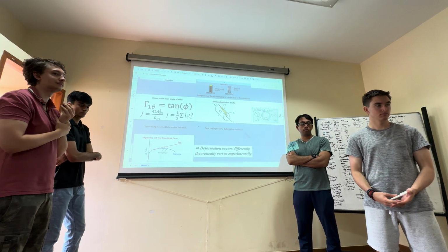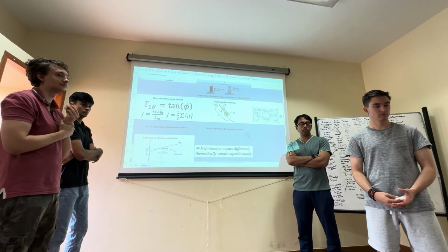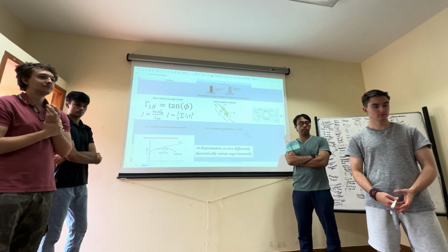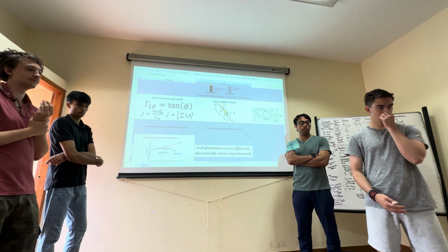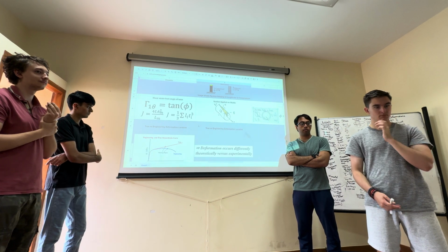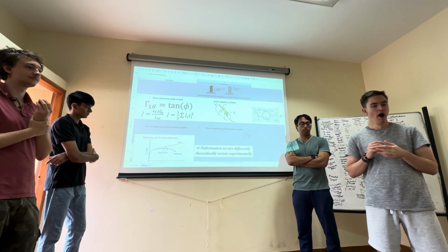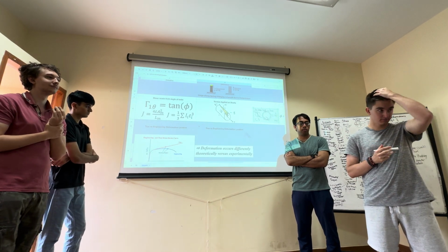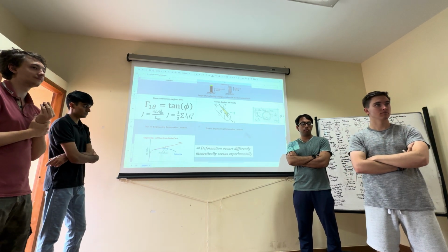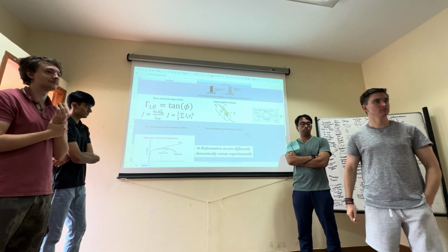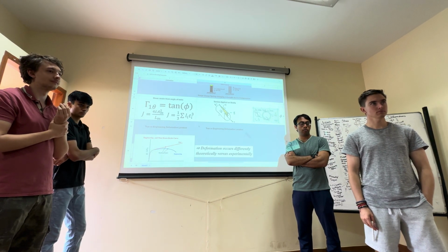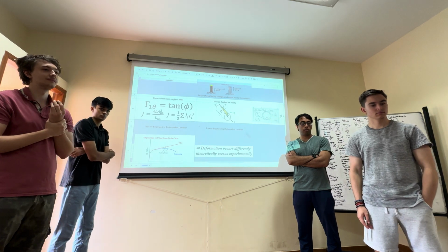So where torques are large, you will prefer to use closed cross sections, because that first J expression will give you a much larger torsional stiffness, GJ, whereas this one will give you a much smaller torsional stiffness, where you want it to be very flexible in torsion. If the torque is not the dominant load and you have other loads which are more dominant, then you still go for an open cross section.